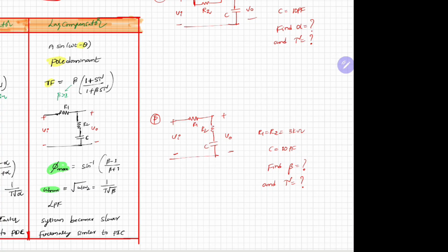What is a lead compensator? A lead compensator introduces a phase lead to a control system, improving its transient response, bandwidth, and stability, while a lag compensator introduces phase lag to improve steady state accuracy and stability. The simple difference between them is that lead compensator improves the transient response and lag compensator improves the steady state response. If you want both responses to be improved, then you go with the combination of lead and lag compensator. That's it. Here I want to explain everything point-wise.